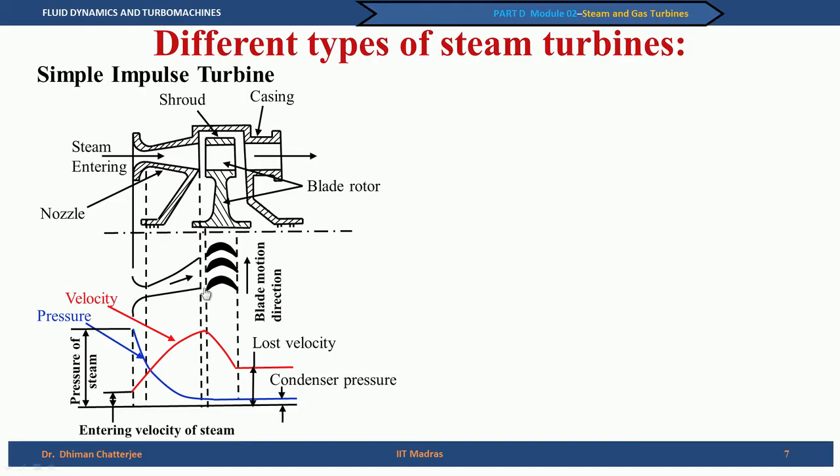You can see these blade profiles. The blade profiles also deserve some special mention. You see these blade profiles appear as if it is a plate which is bent in the form of C. Now, you know that in an impulse turbine the angle of deflection, or the path that the outflow will take from the blade with respect to the incoming direction, will have a large deviation. So, this angle of deflection is large, which is the characteristic of impulse turbine.